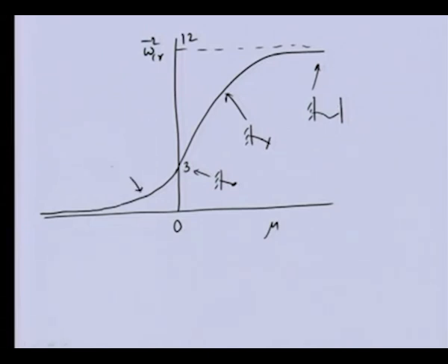Here this will correspond to a long stick, and when we are approaching 0 natural frequency, we will see that this stick is very long, and for a small disturbance it has large displacement because the gyroscopic couple is acting toward the angular displacement of the rotor.